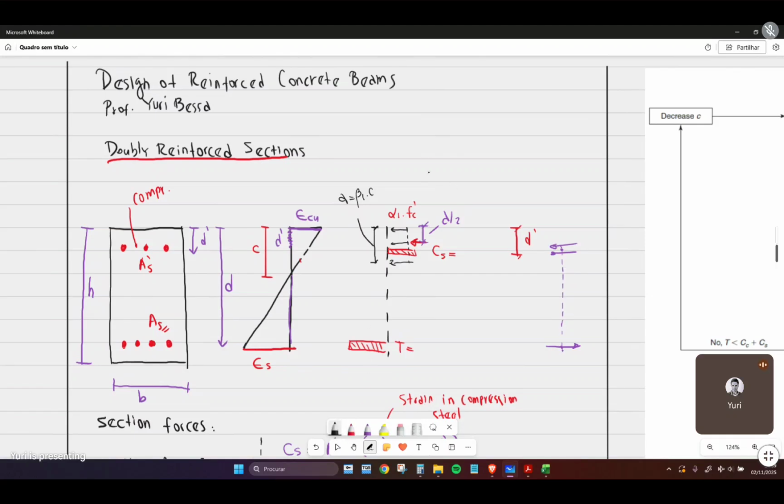So, for example, if we have a regular bending flexure, as we said before, the top face in this situation is the compression, and this one is in tension, okay? So here we would place AS prime, and here is going to be AS. You should be careful because whenever we have a different flexure like this section here, now the top will be tension, whereas this one will be under compression. So don't always assume the bottom reinforcement is going to be the tension one. This is not how it usually works, so you have to be careful.